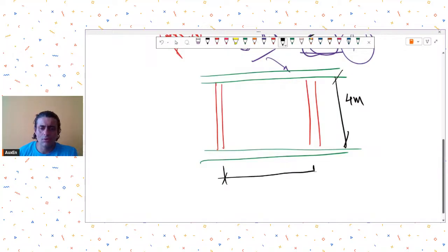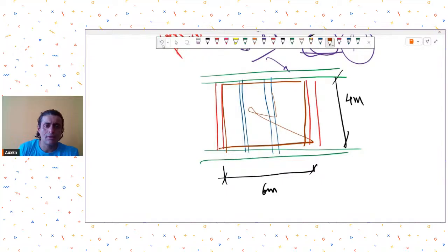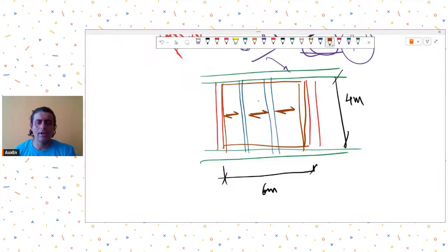Now, if you go on to design a checkered plate for this much span, it will be very, very thick checkered plate requirement, which may not be suitable. So what we do, in such cases, is put some tertiary members for checkered plate support. So now I will put my checkered plate like this, and essentially because I have put my tertiary members in this direction, I can make a checkered plate spanning like this and find out the thickness.